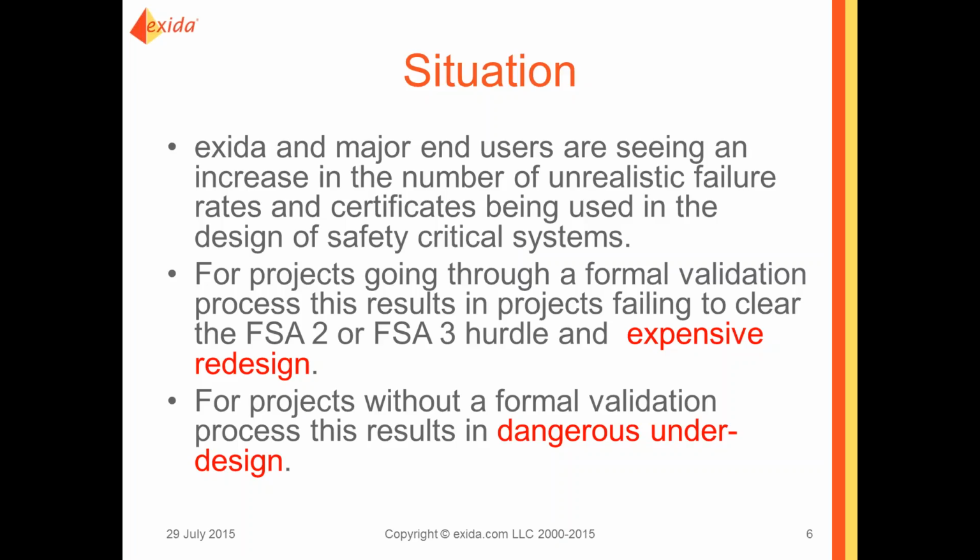Now, we've got firsthand experience from end users who have had to go through this, where they've stopped projects, and we know where other third parties have found discrepancies in the safety life cycle and not allowed plants to start. For projects that don't have a formal validation process, these designs will get into service and essentially result in dangerous under-design of the safety functions. And we'll go through these two options in a little more detail.